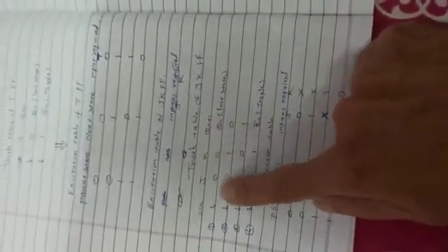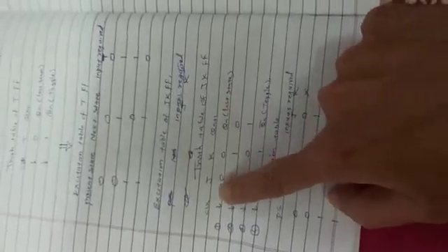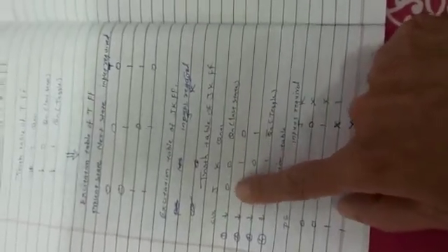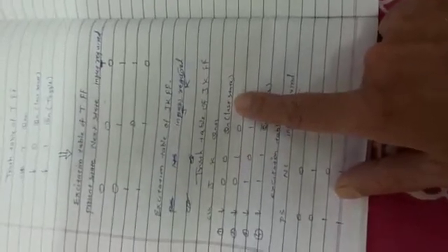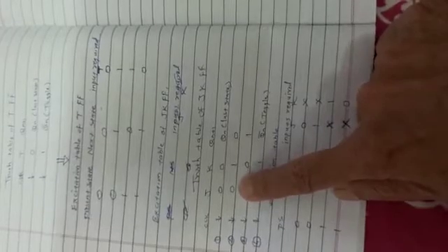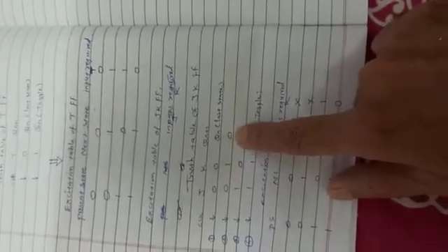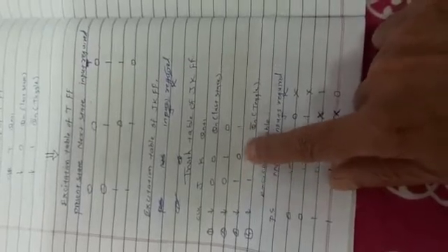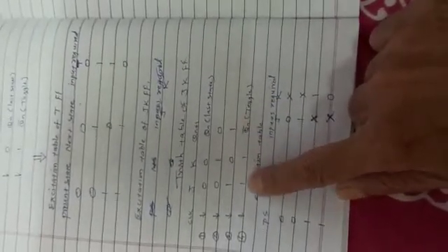So this is a truth table of the JK flip-flop. Here I am assuming my JK flip-flop is negative edge triggered. So if JK inputs are 0 0, it remains in the last state. When JK inputs are 0 1, then it gets reset. When JK inputs are 1 0, it gets set, and when JK inputs are both 1 1, then it toggles. This is the truth table of a JK flip-flop, which you have already studied. Now the excitation table is derived from this truth table.